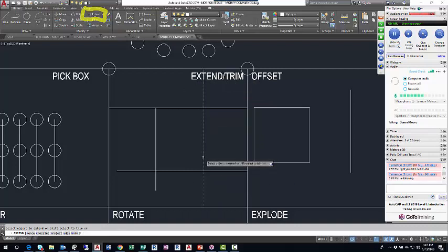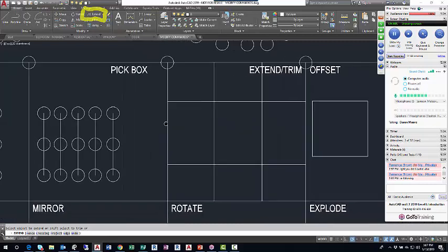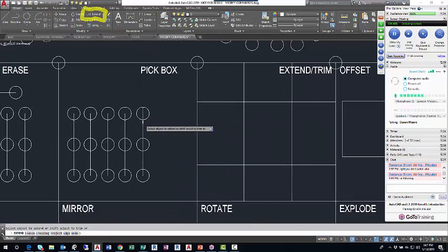I'll just extend all these lines out to contact really the outermost boundary of the trim, extend, or extend trim area. I'll extend this line in the offset area. Right? I'm just extending to the nearest boundary. I'll extend this line to the top edge of the circle, same line, bottom edge of a different circle. So just extending to the nearest boundary edge.